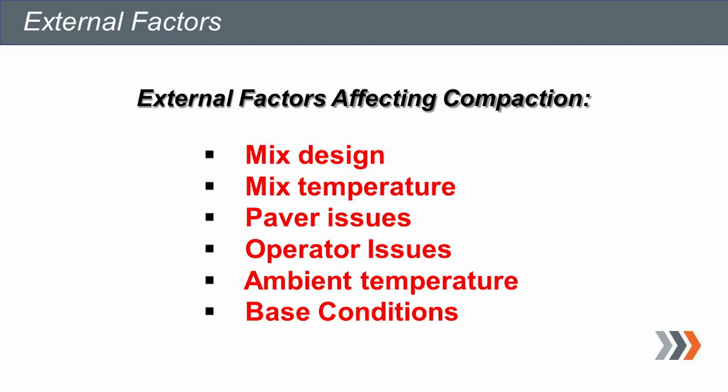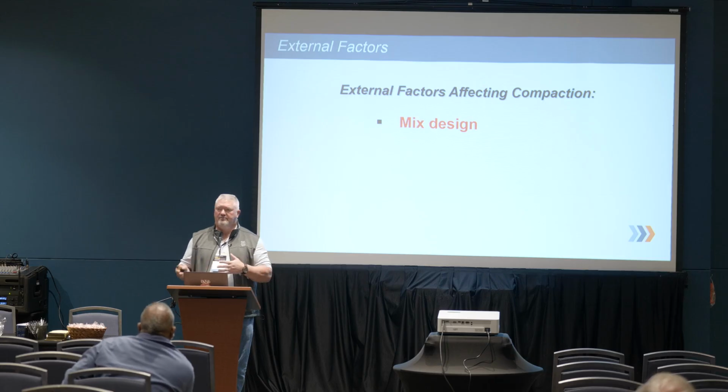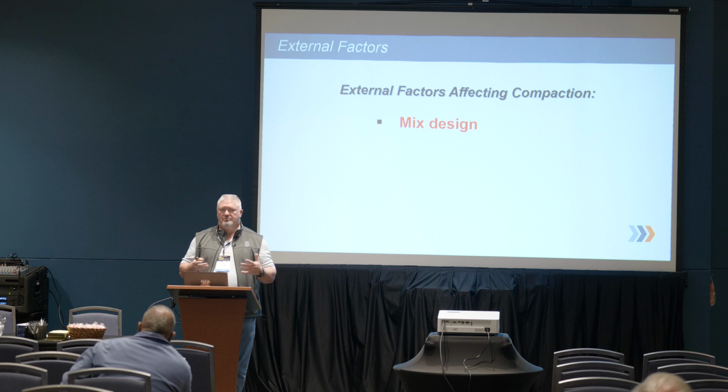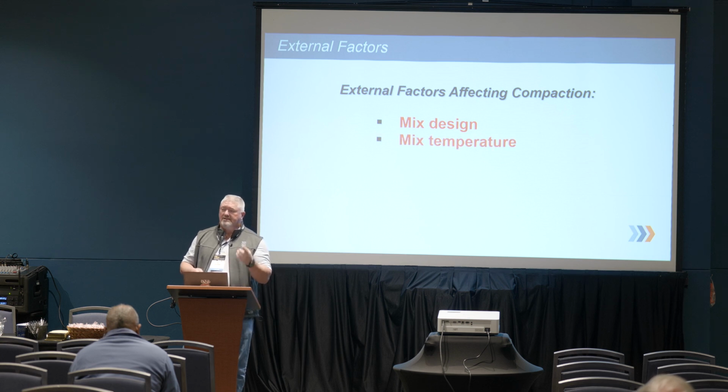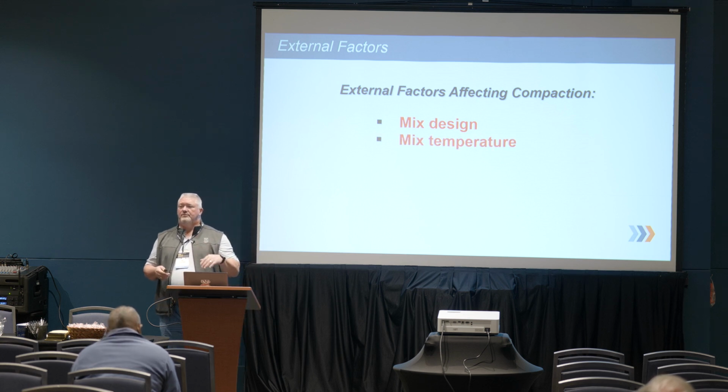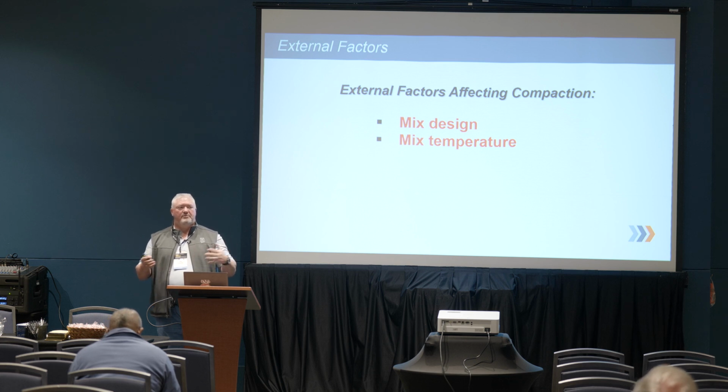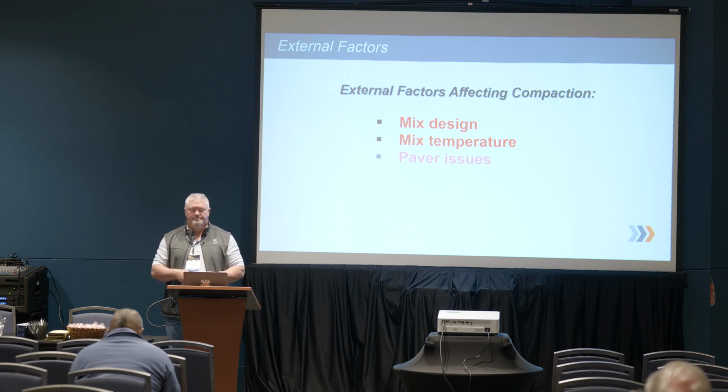Mix design: if the mix changes, a lot of times the good operators will know something's changed. Whether it be the AC content, more fines, or less fines, real good operators will be able to tell by the sound of the machine and the feel of the machine. Mix temperature, again, this is the only thing we can control. If we start getting fluctuating mix temperatures, we don't want to keep jumping around trying to change our rolling pattern because the mix temperature is changing.